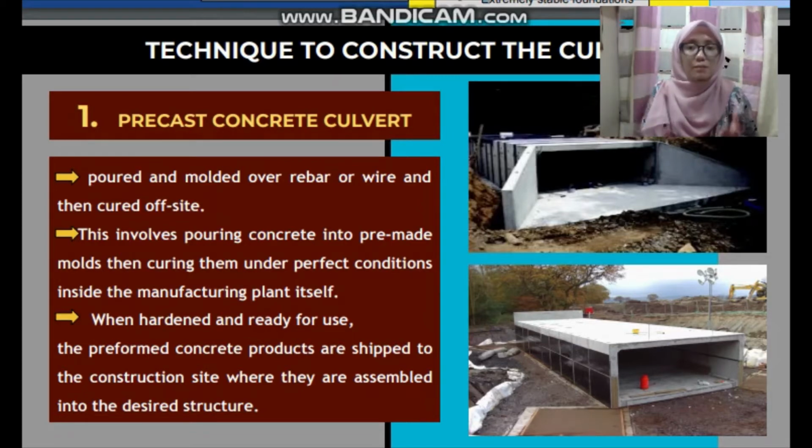First, we can see the possibility impact on all or any matters related to water quality, navigation, wetlands, flooding, agriculture drainage, and so on. And after that, maybe we can see through appropriate stormwater soil erosion control. And for the third, culvert size and placement, fish passage, and flow control during installation. Okay, for the biggest culvert like our project, in situ concrete culverts are cost effective options.